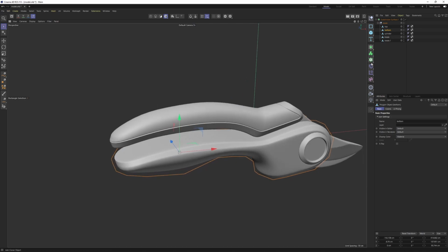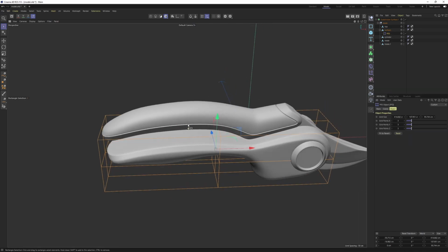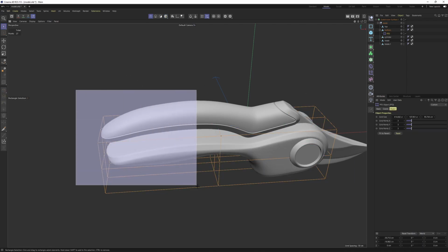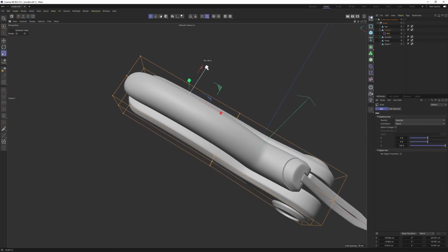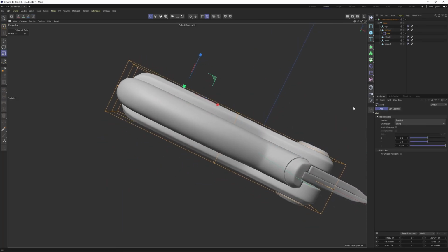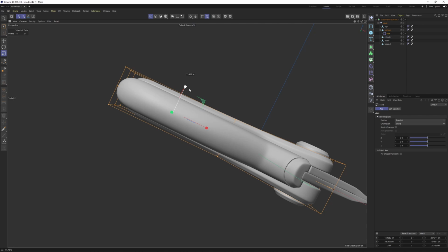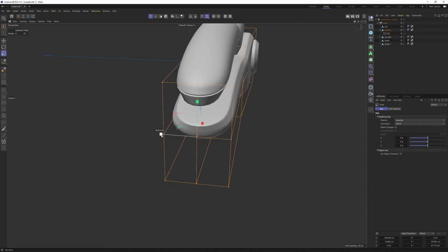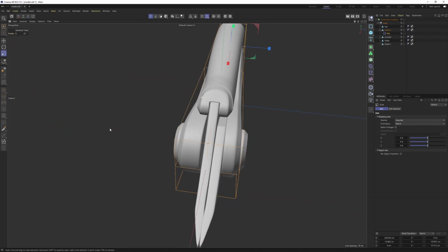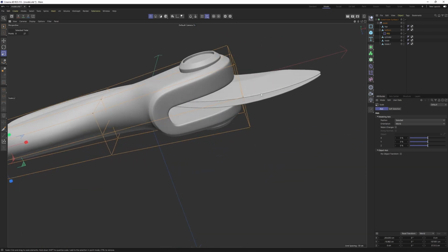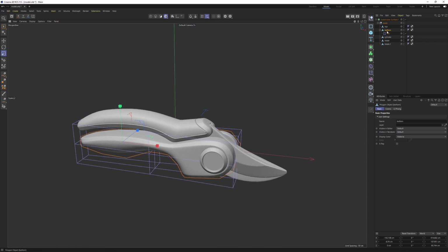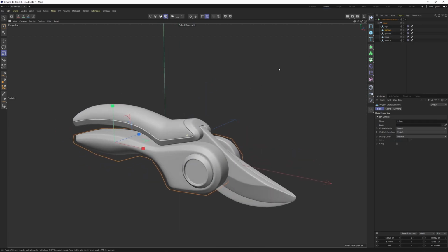play with this more. I'm gonna press Shift, add an FFD deformer to the bottom part. Select FFD points mode. I'm gonna select these and scale them, but we should reset our axis to 0 to scale them from center like that. Then maybe we can deselect this and scale them this time only. Now I can apply that to the bottom object, connect objects and delete.